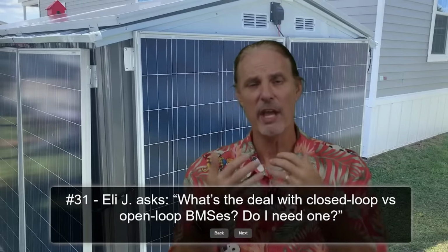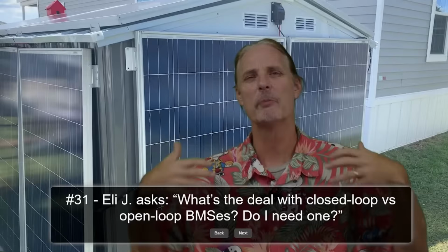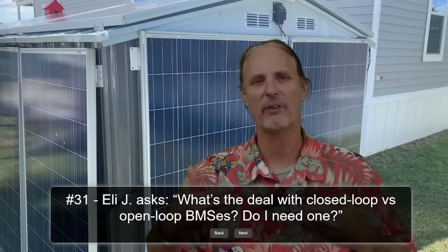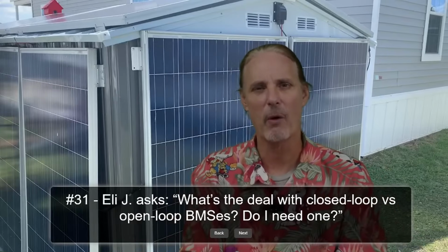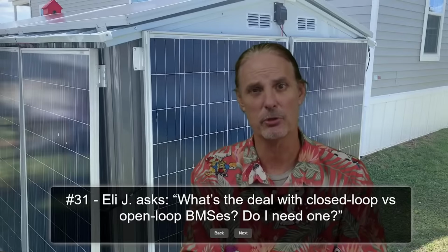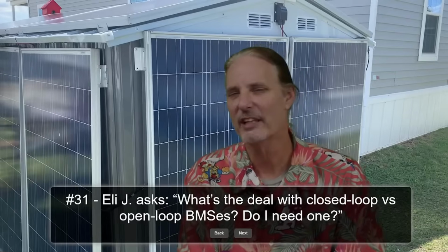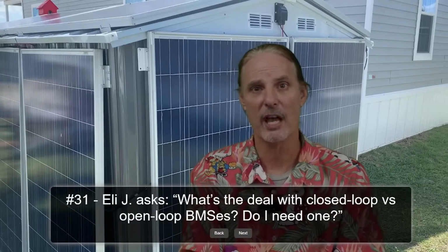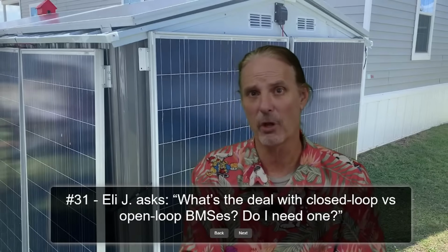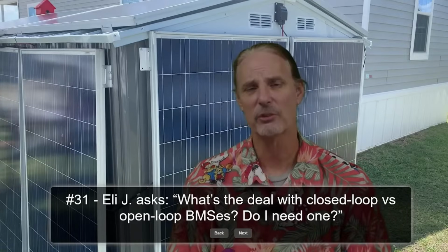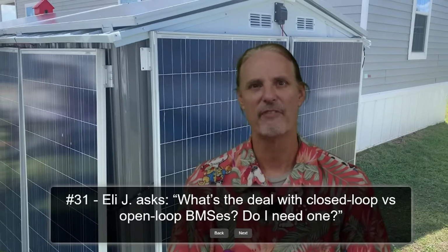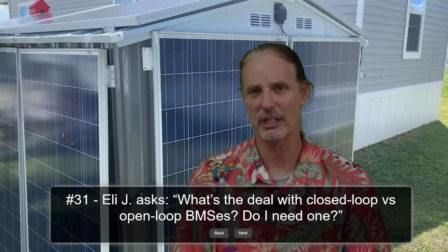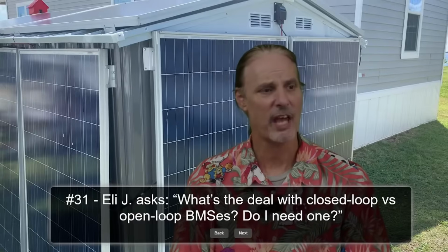Now, that doesn't change the fact that batteries are absorbing whatever energy is made available. But what you don't want is an excessive amount of over-generated power trying to flow into these batteries and cause them damage. There is a limit to what the battery BMS can stop, and the diodes and things can cut off and stop from flowing in the wrong direction. So there still is a reason to limit that availability, even though technically the BMS has cut it off. You don't want to damage it by pushing that much voltage on it if you don't have to. So that is why.